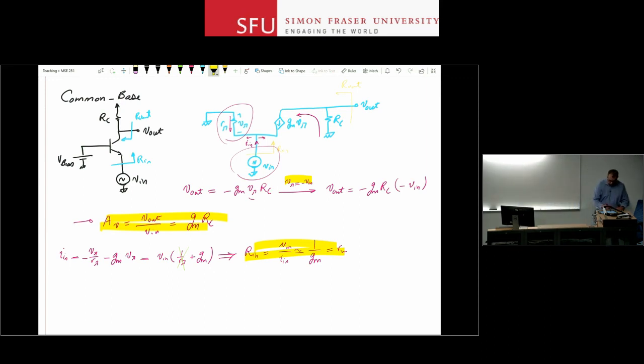And if I want to calculate the output resistance here, of course I have to redraw the circuit for that analysis, because now the circuit is different. The voltage source is applied to a different location. In this case I have the input removed, base grounded, plus and minus V_pi, r_pi, gm V_pi here, and then over here I have R_C and my test source.